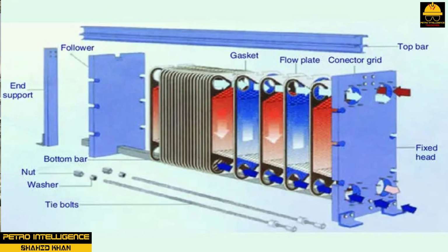Plate and frame heat exchangers are composed of thin, alternating metal plates that are designed for hot and cold service. Each plate has an outer gasket that seals each compartment. Plate and frame heat exchangers have a cold and hot fluid inlet and outlet. Cold and hot fluid headers are formed inside the plate pack, allowing access from every other plate on the hot and cold sides. This device is best suited for viscous or corrosive fluid slurries.